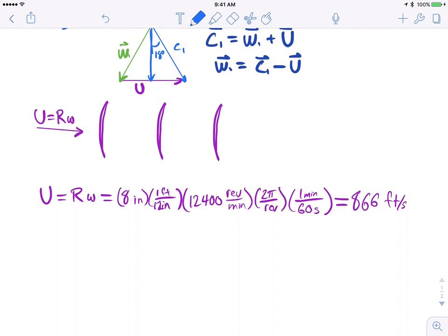So first up, we want to calculate our area. The cross-sectional area of our compressor is going to be equal to, since we don't know the inner and outer radius of our span, we're just going to say it's 2 pi times the average radius, which gives the circumference, times the height of the passage that we're dealing with.